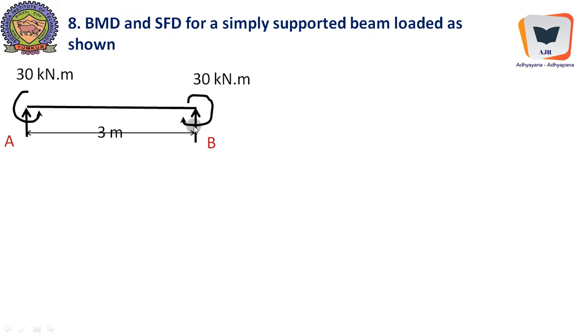And we know how to create a concentrated moment like this over the span of the beam. In fact, we can generate this kind of concentrated moment anywhere over the beam. What we need is to weld a frame like this, a vertical frame, and apply a force like this. Or we can have a frame crossing the beam span and apply a couple, that is a force couple, which can create moment.